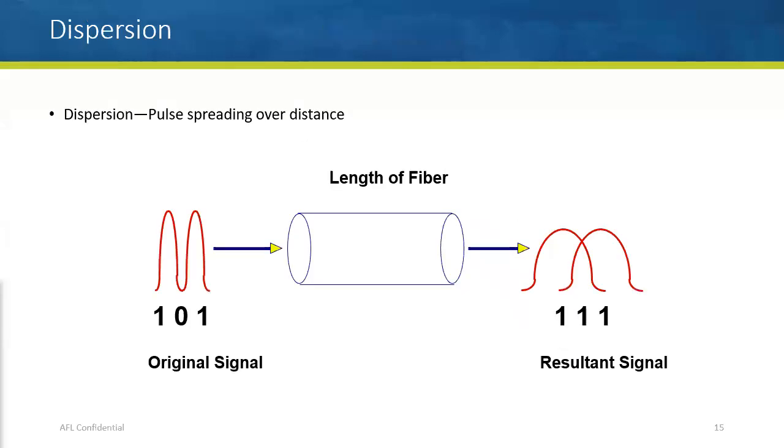One of the other things that we look at is dispersion. That was what we talked about a little bit ago, as the light travels down, some of it gets there fast and some of it gets there slow. And the longer your length of fiber is, the more these pulses overlap. So from the transmitter, you're basically looking at a square wave pulse. On, yes, there's light. Off, no, there isn't light. And doing that as quick as possible. And by the time you get to the end, you end up with these pulses that may overlap a little bit. So there's always some light, but it's not always at the peak intensity.